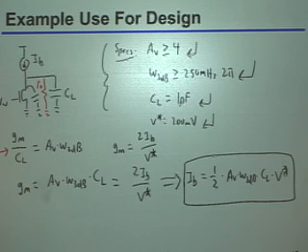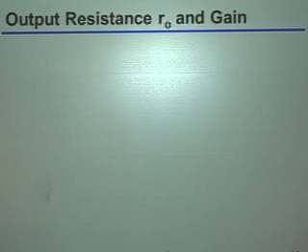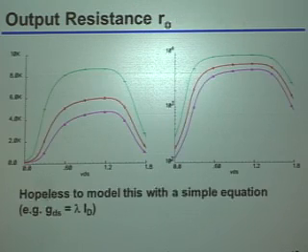Okay, so with that in mind, let's take a look at the output resistance itself, but more importantly, what it implies about the DC gain you can actually get. This is really just a reminder from last time. This is showing you, not for our particular technology but for some older technology, a plot of what happens to the output resistance of some device in different corners as you sweep the VDS across that device.